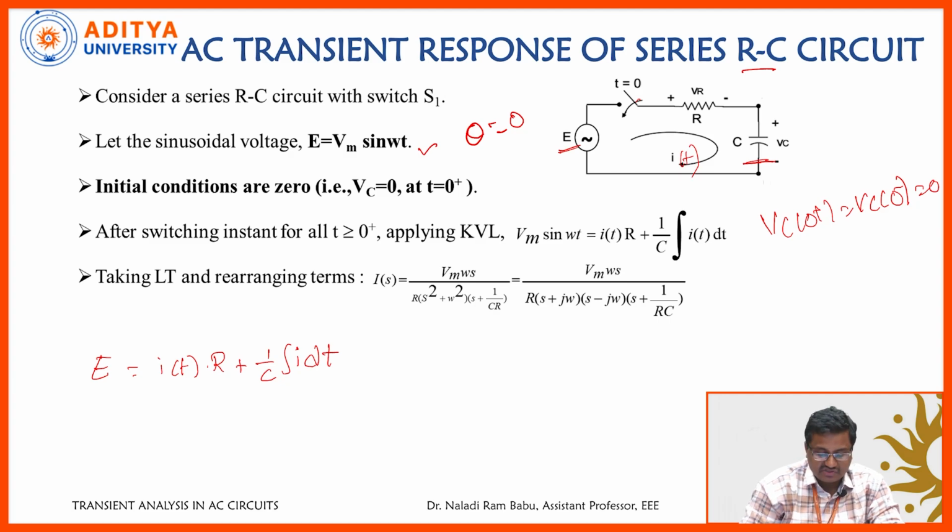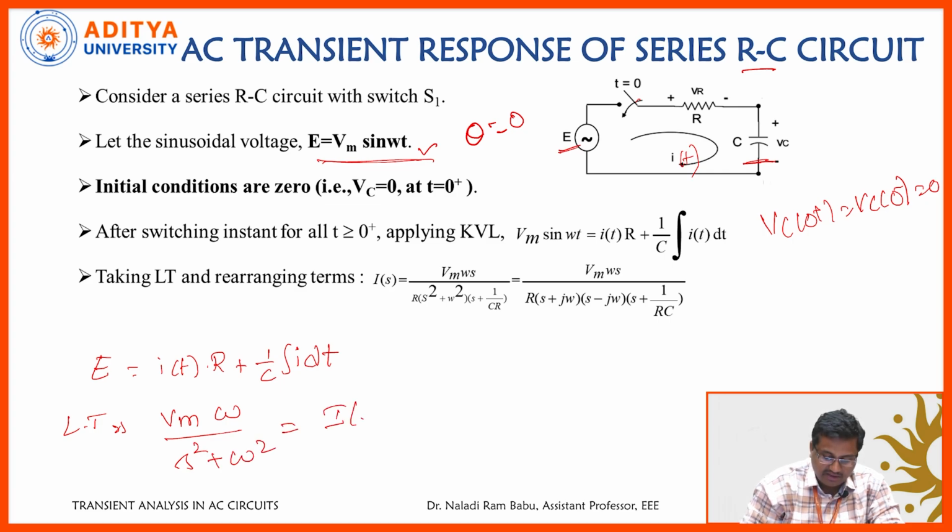Now if I apply the Laplace transform, E is Vm sin omega t, so for Vm sin omega t, the Laplace transform is Vm into omega by s square plus omega square. That is equal to i(t), which becomes I(s) into R, and 1 by C integral of i dt becomes I(s) by s.